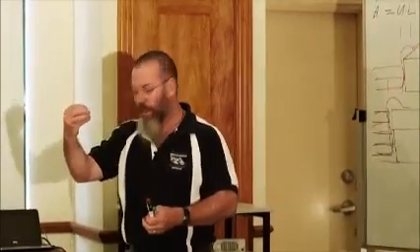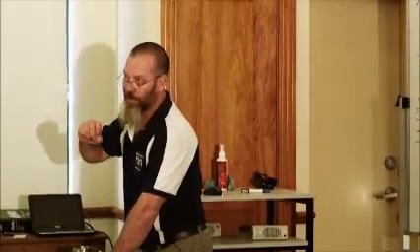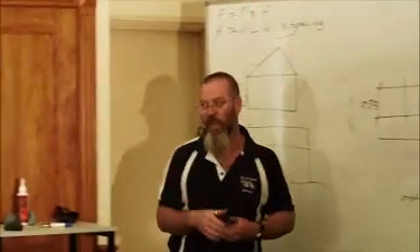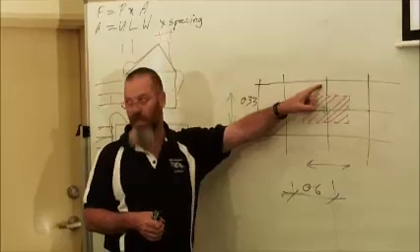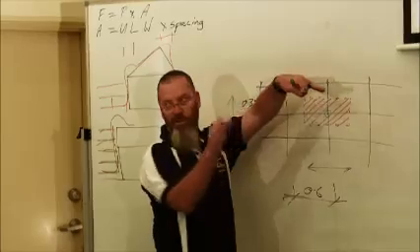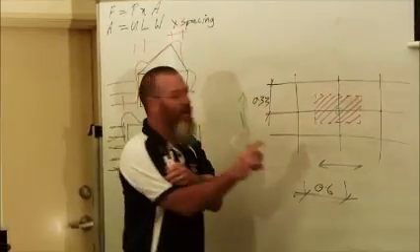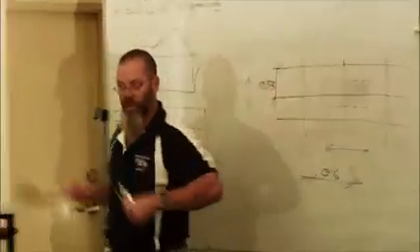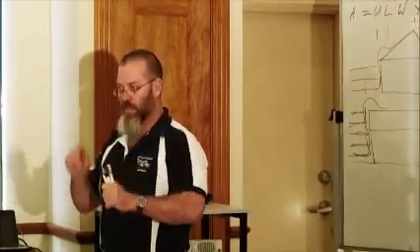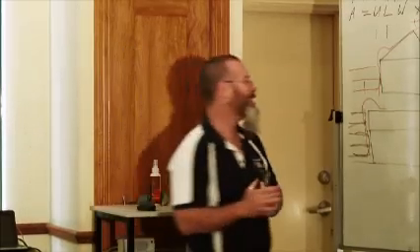So that's what edges are. Edges aren't just the fascia or the barge. They're also the ridge and the hips. Okay, you just got to stick with the definition I gave you back there at that other slide. Every connection within 1.2 metres. Technically, what you're saying is, if this was the fascia here and you've got a connection there at that point, it's really only half that tributary area, isn't it? But because we need to wipe that out of our head, we just work on this one. We'll do one area, which will be 330 by 600, and that'll apply over the whole roof, assuming your batten spacings are the same. We're doing construction in heaven. Your batten spacings will be the same. It'll be perfect.